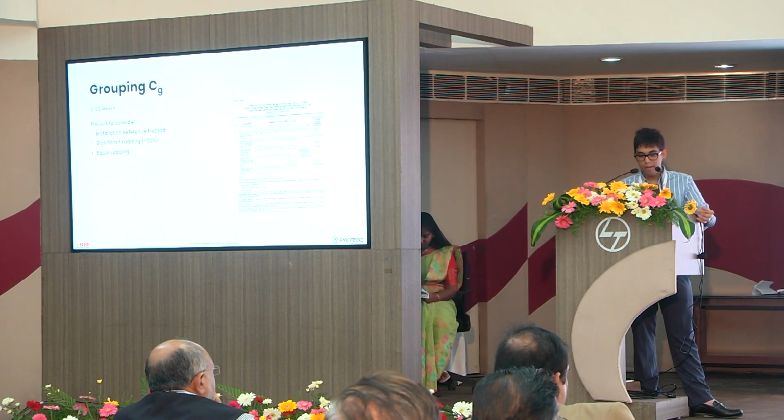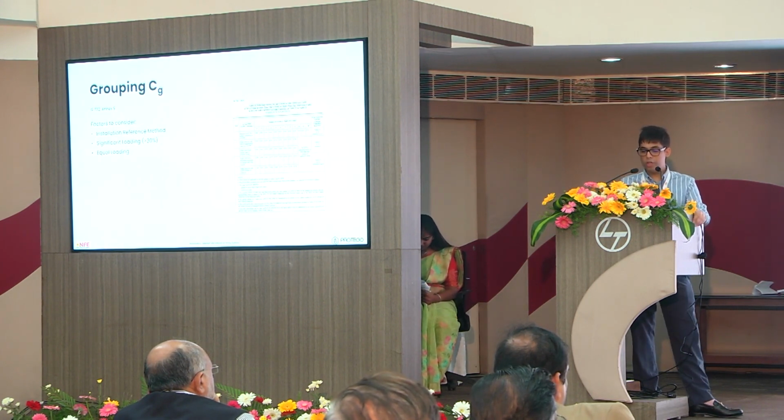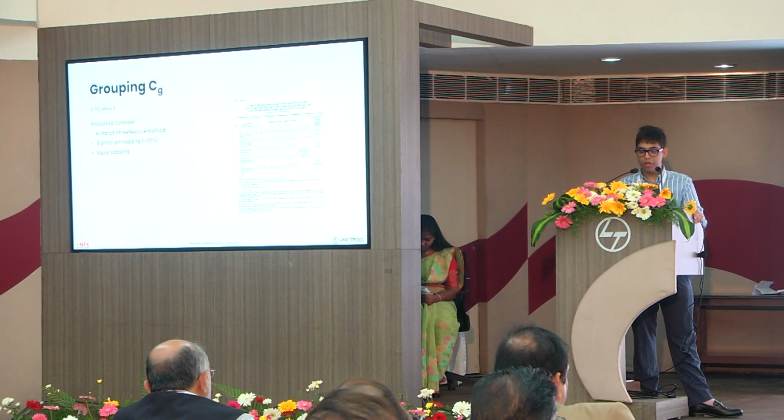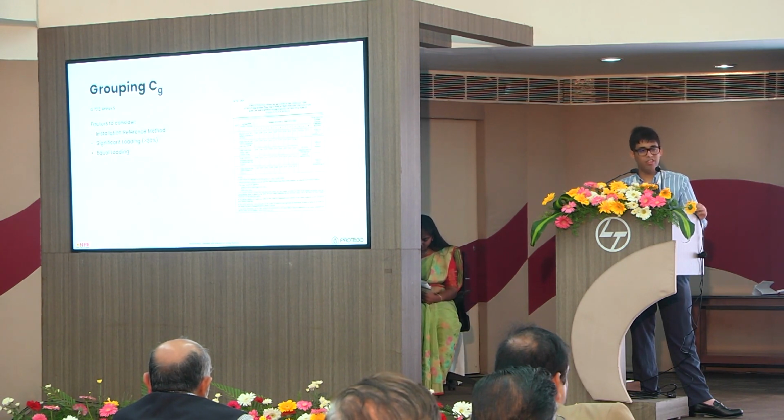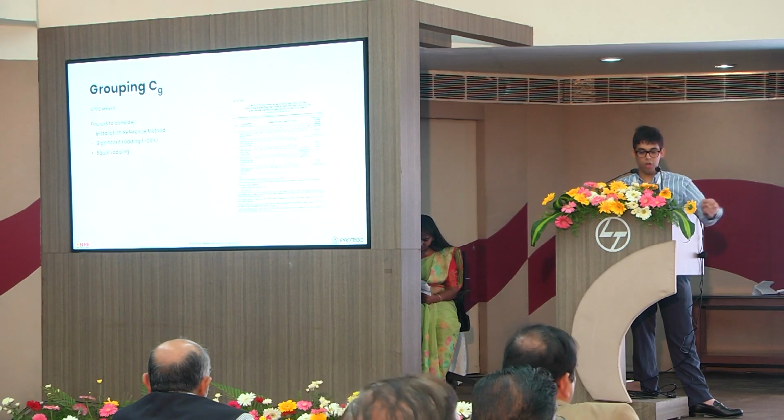So grouping, firstly, like I said, multiple circuits together means increased heat, and it is much more difficult for the heat to dissipate. But please note, the grouping factors only have to be applied for cables that are loaded to more than 30%. Because if the cables are not loaded to more than 30%, there is no appreciable thermal strain that is going to have an effect on the other cables.